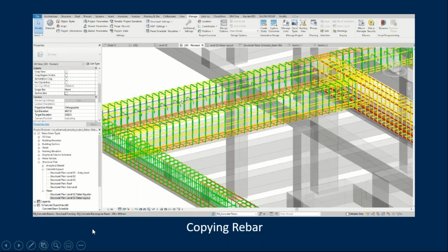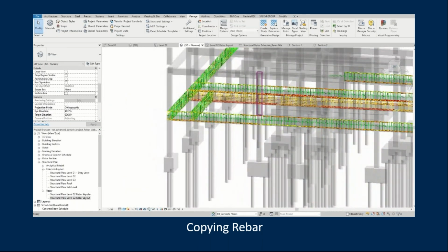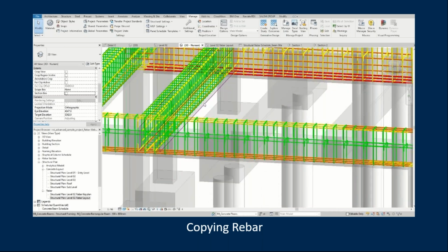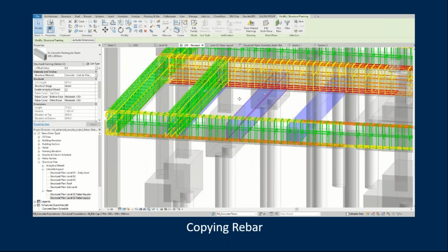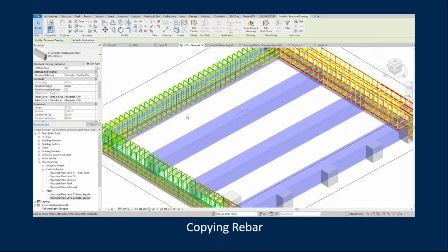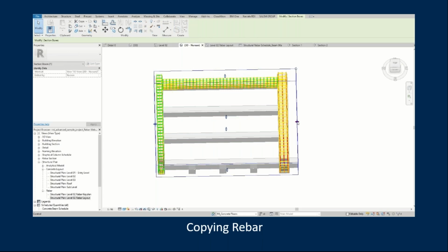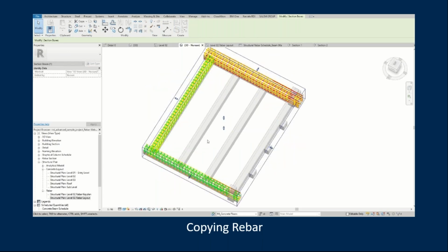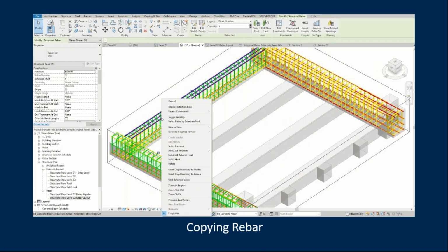Okay, so I'm just going to expand this to see the full floor. I'm going to look at this one panel and isolate the beams that are similar. So those 3, and select that one also. And then I can either click on the box tool or type BX, which is the shortcut. And I'm just going to extend the side over here. So that last beam is actually continuous, so it's not exactly the same as these simply supported ones.